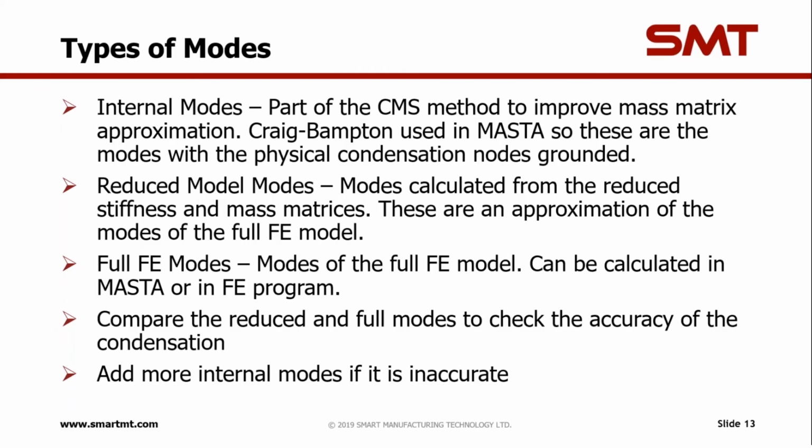In the method that we use in MASTA, and is usually the default in most FE packages, these are calculated by grounding the physical condensation nodes. These are entirely part of the approximation method. They're not used for anything else apart from that.